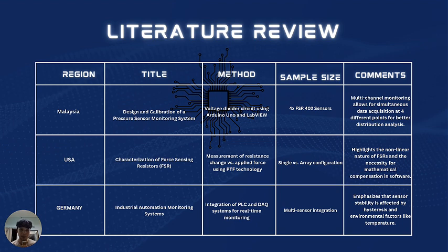The method is measurement of resistance change versus applied force using PTF technology and sample size single versus array configuration. For the comment, it highlights the non-linear nature of FSRs and the necessity for mathematical compensation in software.